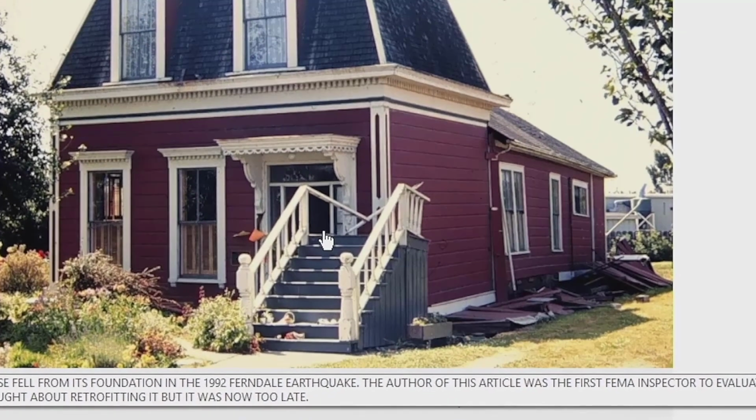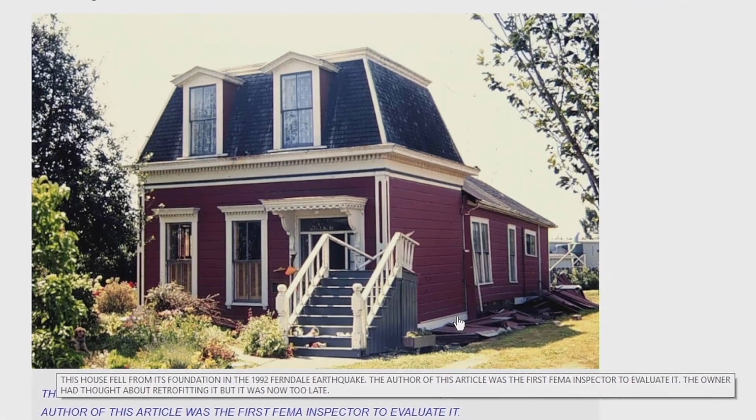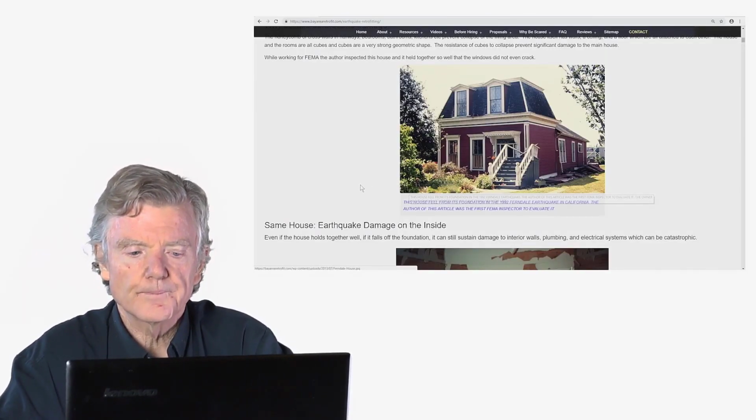So here are your steps right here. They used to go into the front door. Front door is hidden behind there, and then this is the floor of the house where people used to walk around. So this is very serious damage, and again, this was cripple wall collapse. If the cripple wall had been braced, you wouldn't have had that kind of problem.